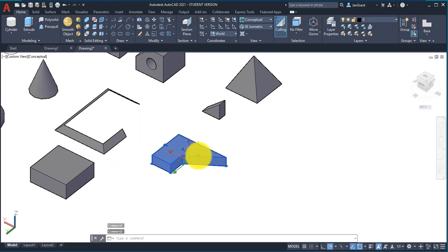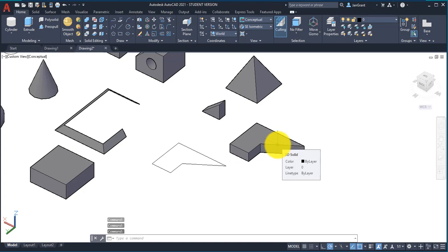When you use press pull, in this example we worked with earlier, the solid shape is separate from the original line work. And extrusion, you can see over here, consumes the line work. So let's say you've got some 2D geometry and you're ready to make it into a solid. If you use press pull, the 2D geometry will still be maintained. If you use extrude, the 2D geometry will be consumed with the command.